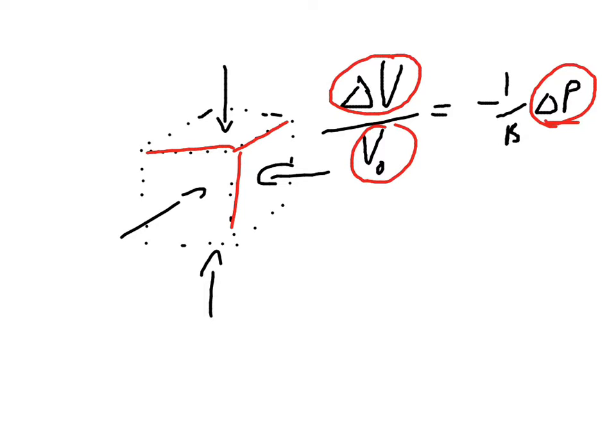So if you jump to slide 14, there are some ultimate strengths. And you've got them in tension and compression and then in shear as well. So obviously what you want to be thinking about when you're picking the material you're going to use is how you're going to use it. Because if you see concrete, under compression it is very, very good. Under shear or under tension, it's not so good. Still pretty good, but it's not so good. That's probably the one with one of the biggest differences.